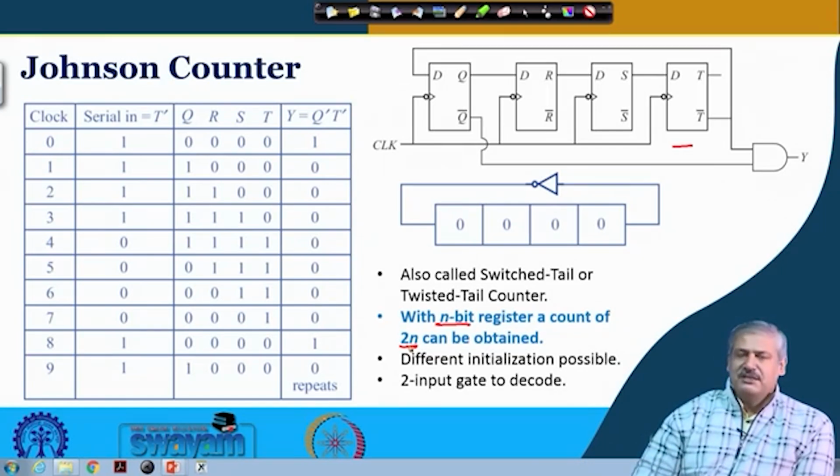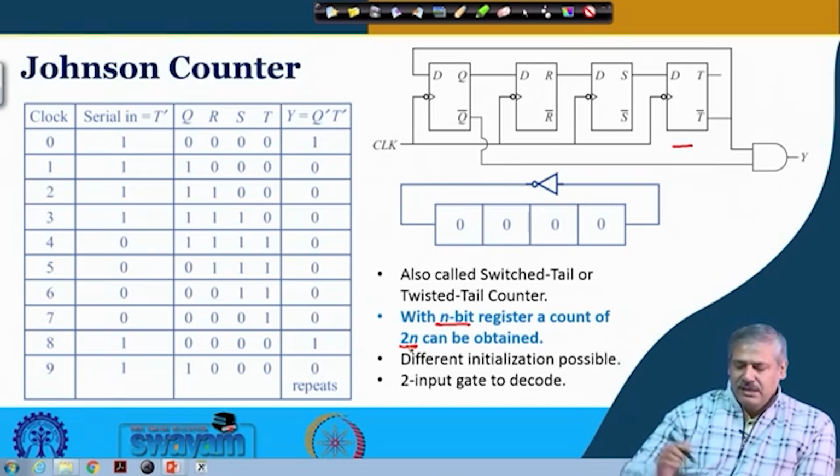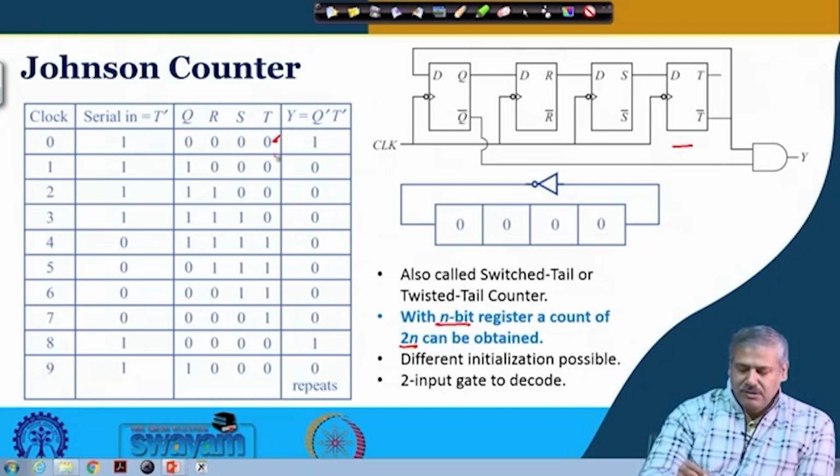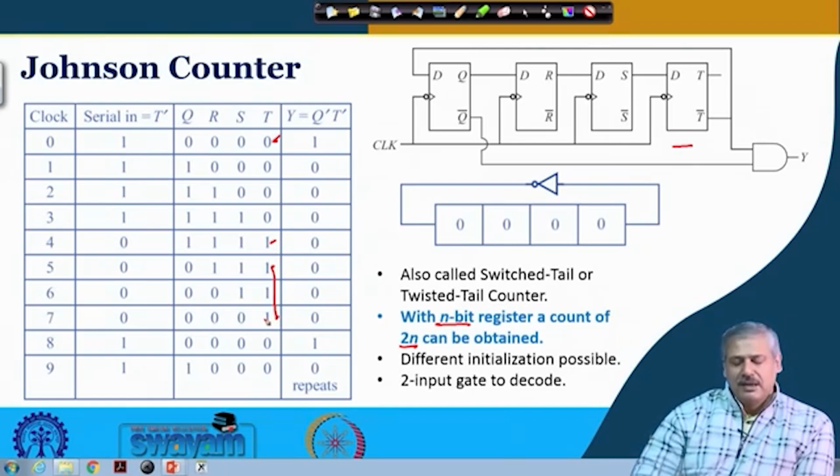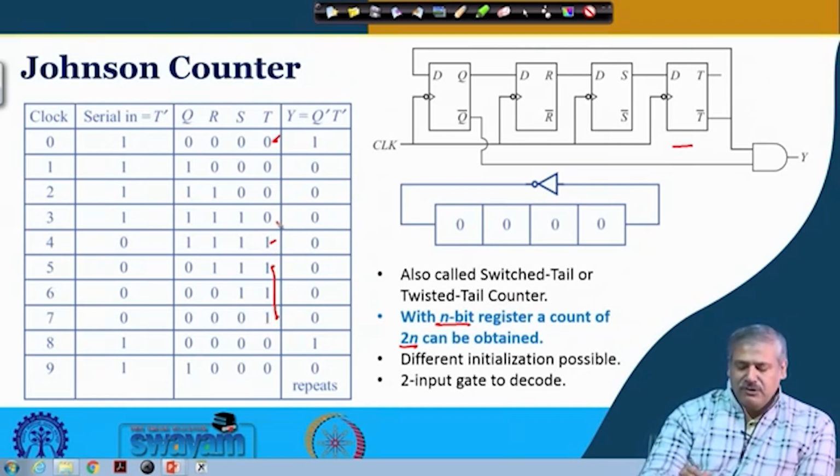Okay. So in the ring counter we saw that no other external circuit is required. The output flip flop directly can be made available to the outside world, and whenever it goes high, that means a count of 8 has taken place, isn't it? But in this case, if you consider a similar scenario, say T is 0, over here it is 1, but it remains 1, and again it will become 1 after 4 clock pulses.